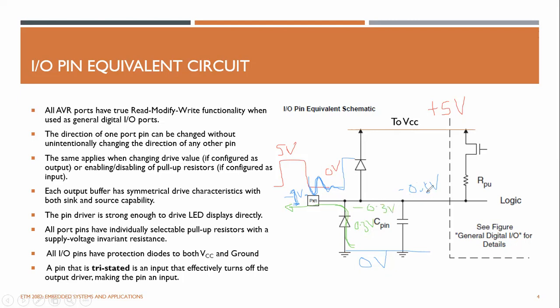Okay, which means it doesn't exceed minus 0.5. So this pin will be safe. Whatever the extra voltage will be dropped inside this PCB traces, and likewise -1 will be here, and the rest of the voltage, -0.7, will be dropped across this PCB traces. So that's how the lower diode will protect the microcontroller from negative voltages.